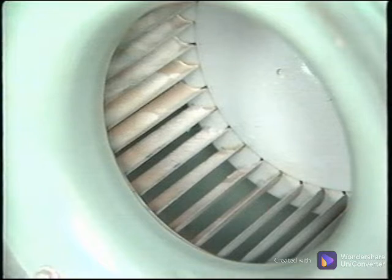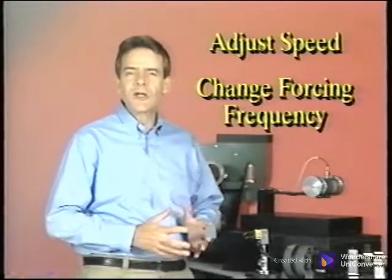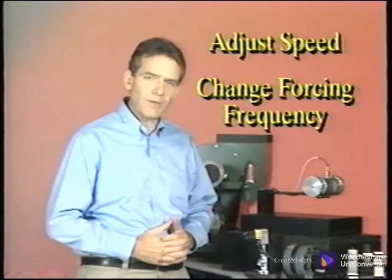If resonance on a fan is at blade pass frequency, change the number of blades on a fan. If the resonance is equal to the frequency generated by a coupling, change the coupling type. If the resonance is a multiple of the belt frequency, change the sheave size or belt type. Adjusting the machine speed or changing the forcing frequency are the two simplest methods to correct a resonance problem.